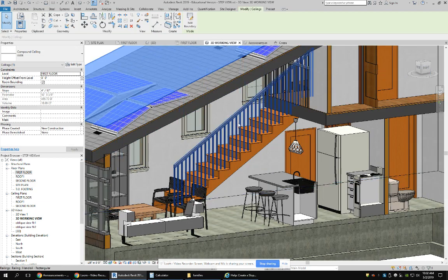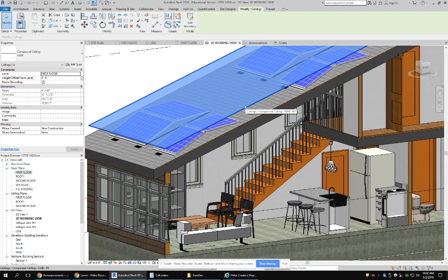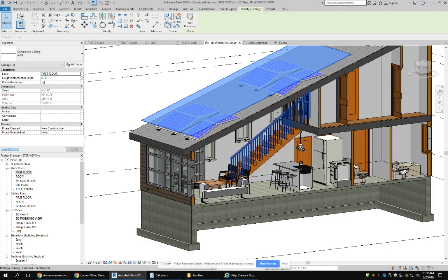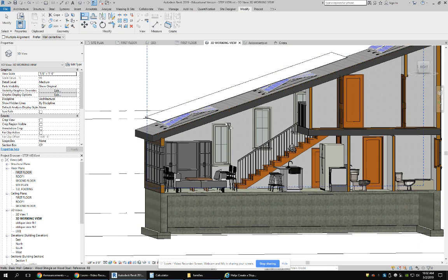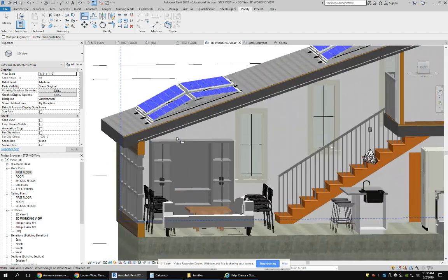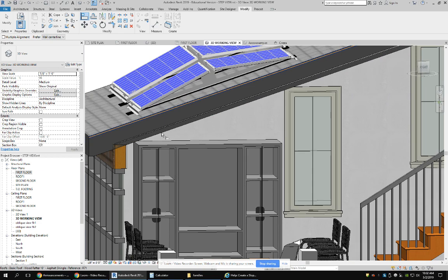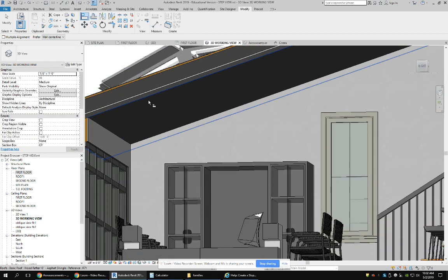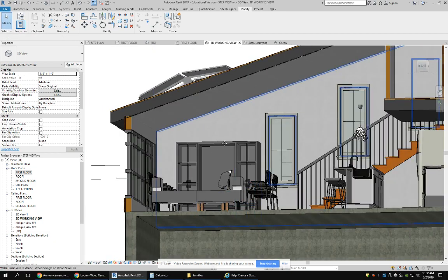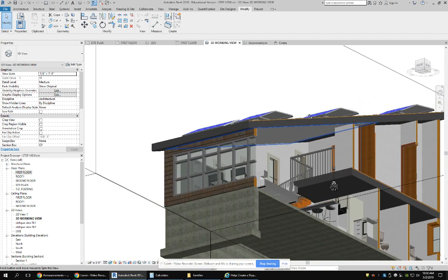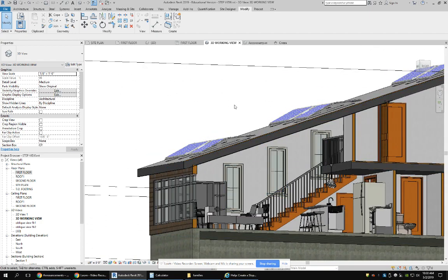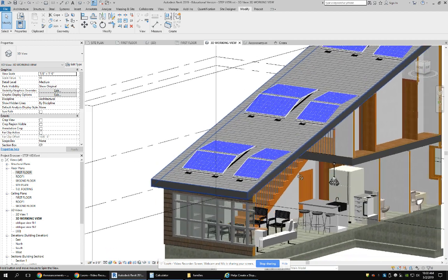We'll go to the 3D working view, and it did, but the height of the ceiling is a little too high. And I believe we can fix it by just using the align tool. So I'm going to align the bottom side of the rafter with the top side of the ceiling. See if that worked. Looks like it didn't quite hit the right spot, so let's try that again. We'll use align, hit that edge and this edge. There we go. And now we have a ceiling that's attached to the underside of the rafters, and I should be able to place those track lights now.